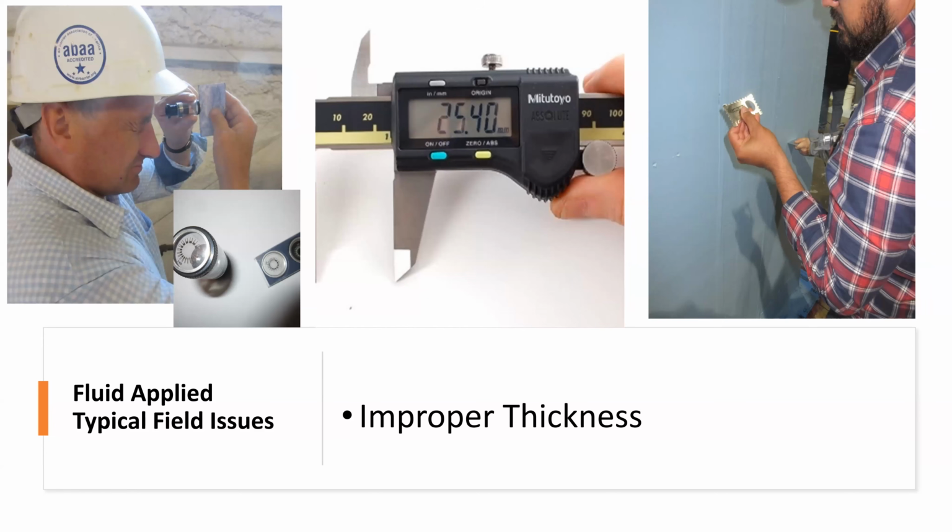Okay, so how do we check for thickness? Well, there are three different ways. The easy way is a wet mil gauge. While the installer's applying, you have this little wet mil gauge that's going to say, hey, it's 20, 30, 40. Super easy to do, and can be done throughout the construction project.